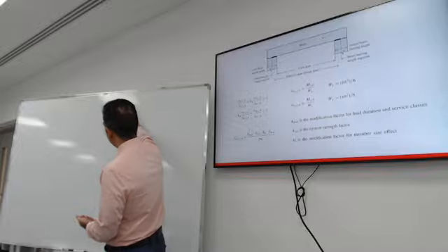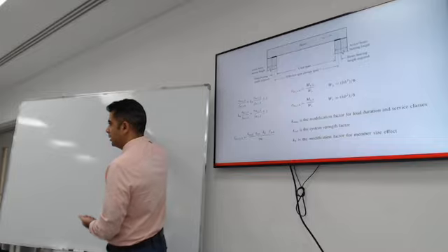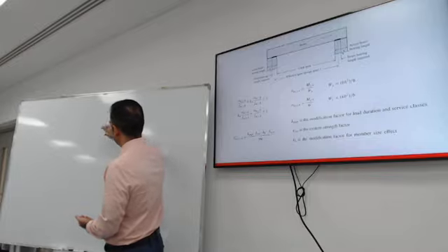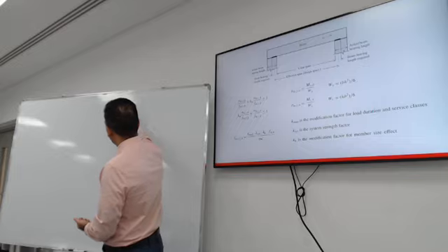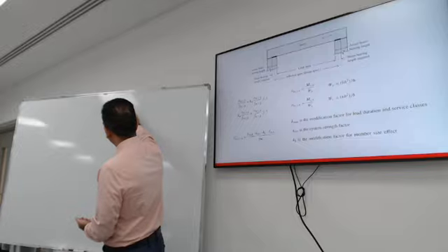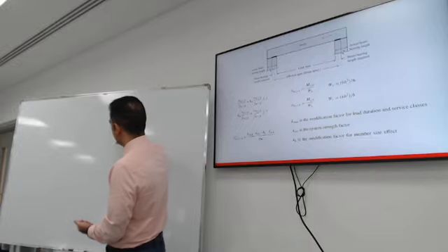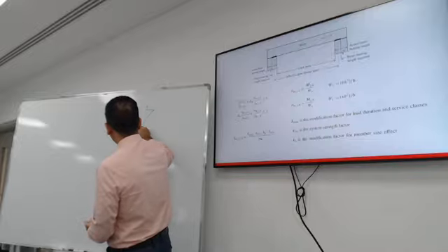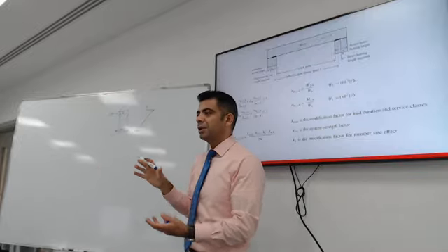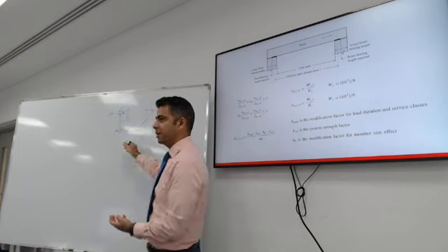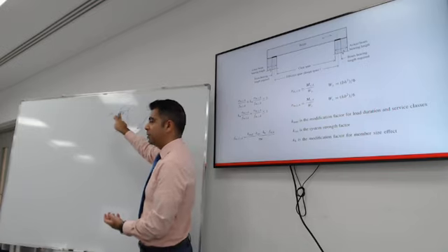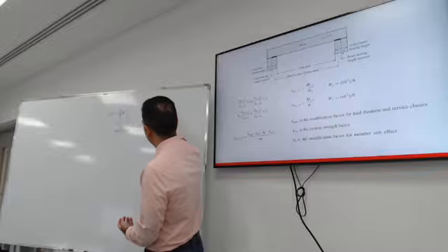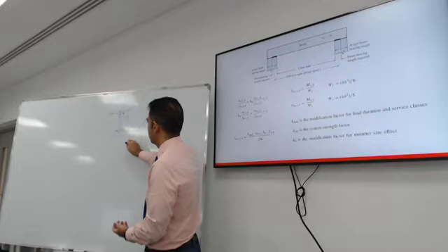Well, if you get the height or effective height of the section, you can translate the moment into a couple that will create, at some point here, everything above this is compression, everything below it is tension. That's why the distribution is linear, not in plastic stage, in linear stage, the distribution looks like this. If the tip of the arrow is going into the section, this is compression. So this is stress in compression. This is stress in tension.